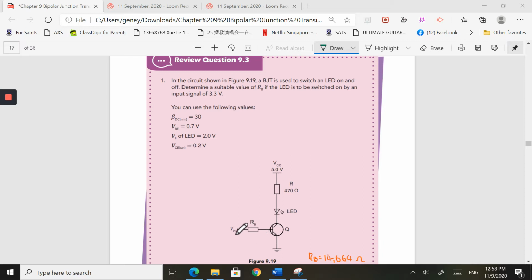That means I have a voltage coming in here, and because there's a voltage coming in here, I'm going to switch on this LED. So instead of pressing your finger down on a traditional mechanical switch, I'm going to have a voltage in here. It turns on this LED. Acting as a switch is this BJT.